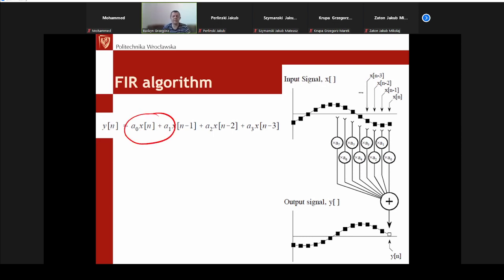And then we come to a very important element of digital signal processing. Going down to microcontrollers, forming the digital signal controllers, the major operation available in DSP-aware microcontrollers, or digital signal controllers, in other words, is a single cycle, or very fast, or optimized multiply and accumulate: integer, fractional, and/or floating point, because these are three different types of operations available.